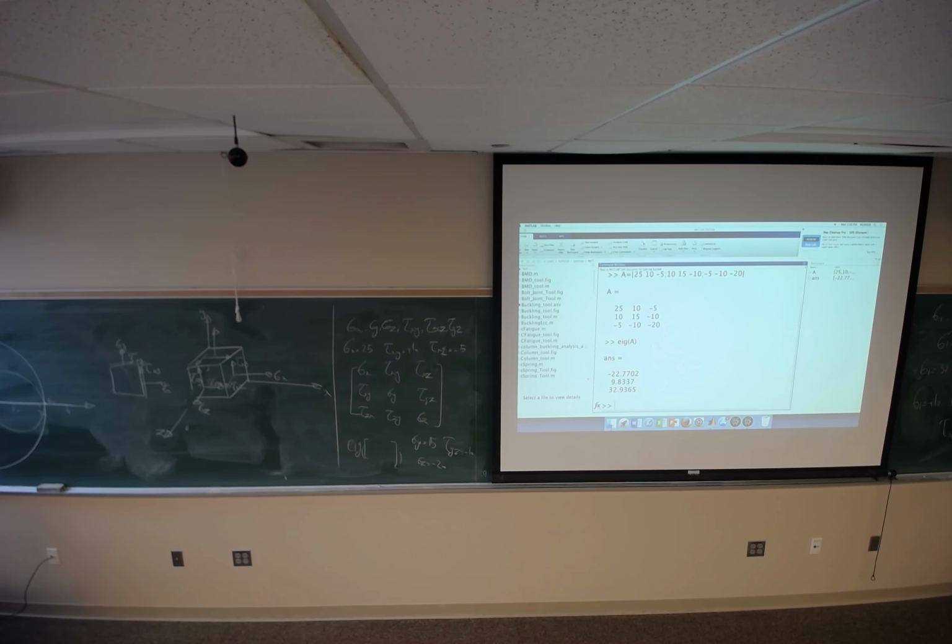If I ask you what would be the maximum shear stress, you can say, I'm going to look at the largest circle, or greatest circle, and the radius of that circle is going to give me the maximum shear stress. The largest circle is going to be this. The radius of that is going to be sigma 1 minus sigma 3 divided by 2. Good?